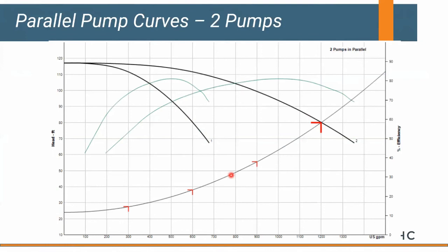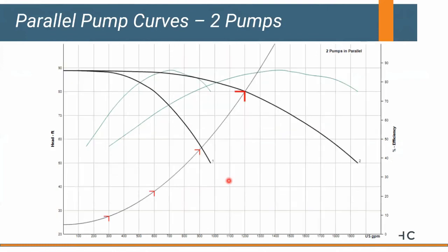So in evaluating a pump, we want to make sure that individual pump crosses the system curve. So this second selection might be a better choice for us. Now we could run 2 pumps in parallel. If we decide we're going to shut one off for either service or just for staging potential, you notice that a single pump doesn't run at 600 gallons a minute. If it's in operation, it has potential to run out here to 900 gallons a minute. Well, that's about 75% of what our plant requires at 1,200. So one pump will give us about 75% capacity. That's really great as far as parallel operation goes.